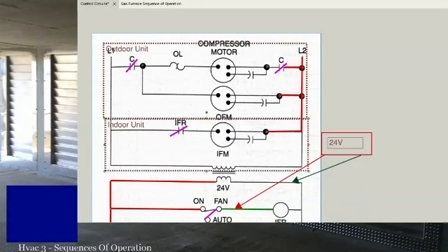Or basically anything else that can cause a heat problem. You might even just have it open on a really hot day, especially if it's an older unit or you got a dirty coil or something like that. It could just open because everything's running hot in general and there's a high load. In general, though, overload opens if you're not cooling the condenser, or you got way too high superheat from the evaporator, or you're drawing very high amperage.